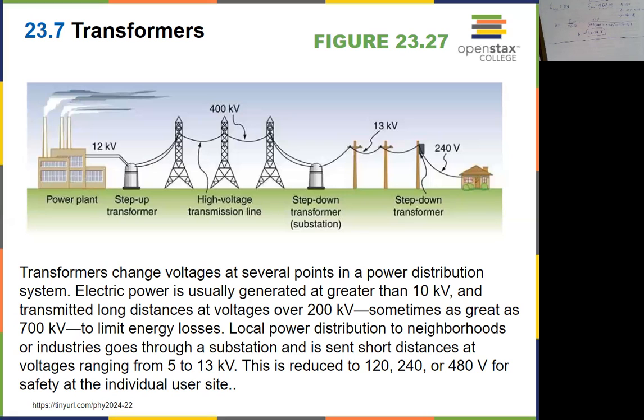Anyway, for the power plant, usually it comes out with high voltage. Before it's transmitted to the household, it usually travels a long distance, right? We can be using electric power from, say, maybe Colorado. So it travels a long distance, and transmission of electric power over long distance is via high voltage. If you have high voltage, then the dissipation of energy on the way is smaller,